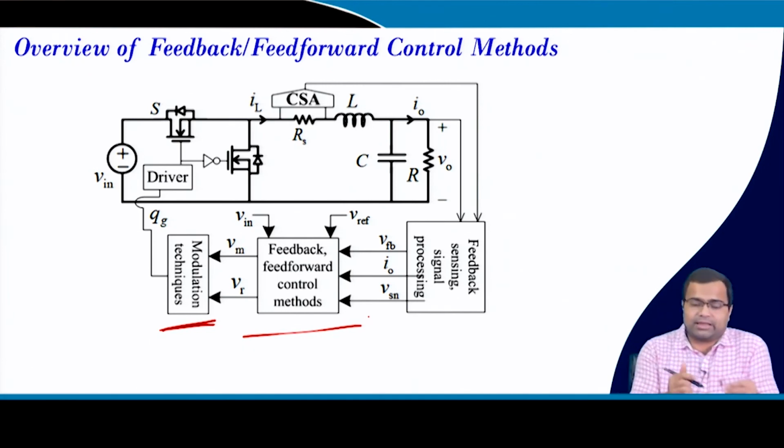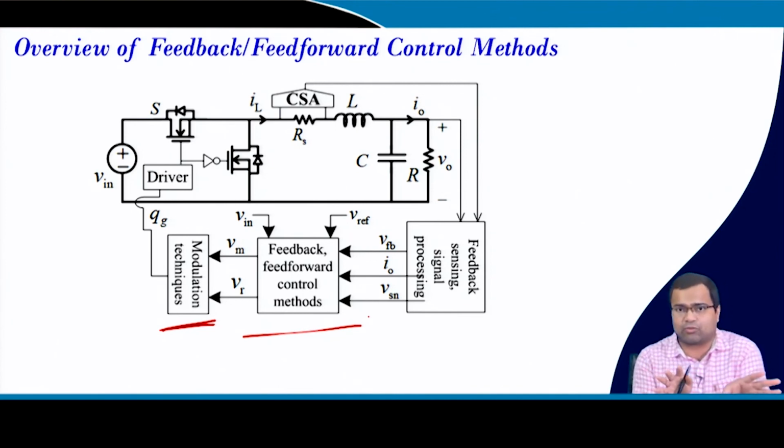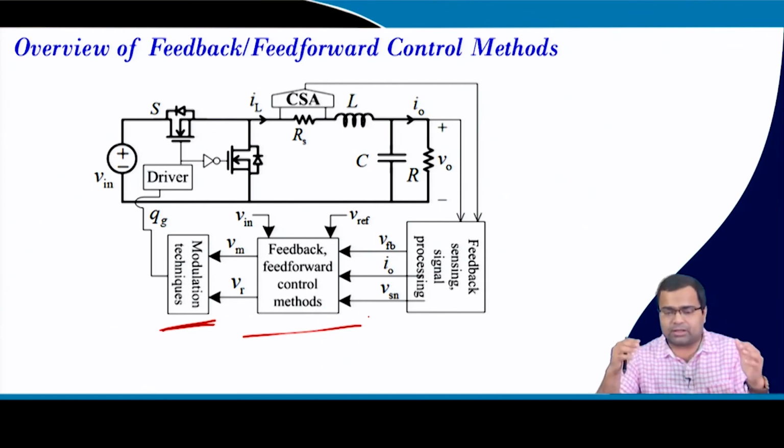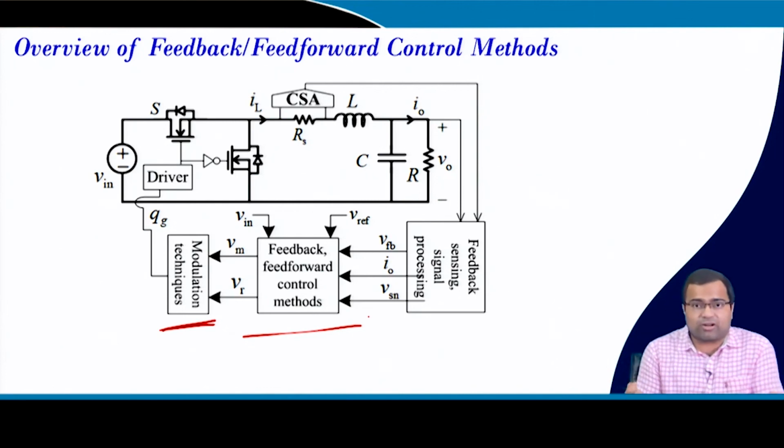Similarly, by means of modulation or control, we can do active EMI reduction by means of frequency modulation. So, all this can be incorporated into the control. Control can play a significant role in improving performance, in achieving close to zero output impedance, and in achieving fault protection, I think a fault tolerant power converter.